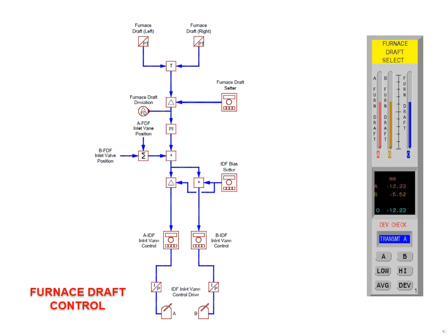And for the furnace draft control, there are a number of features associated with this control, which acts directly on the induced draft fan vanes on discrepancies between the furnace pressure measured signal and the set point. There is a deadband setting to prevent overshoot of the pressure as well as a necessary response to small transient deviations. There is also a feed-forward signal from the forced draft fan controller, the one that we reiterated earlier, to the induced draft fan controller to ensure steady control.